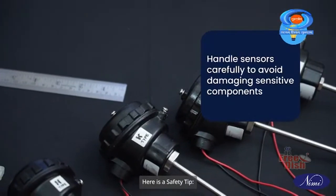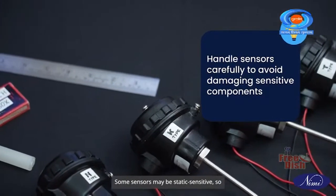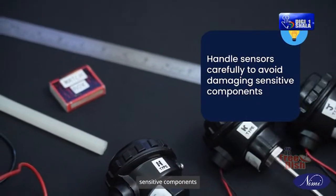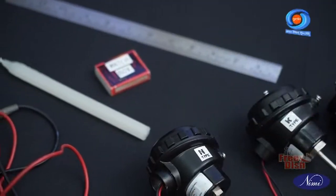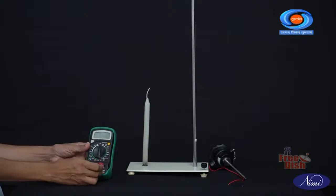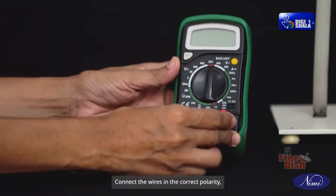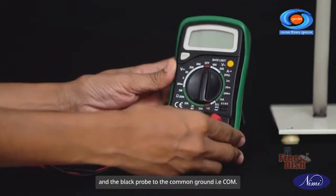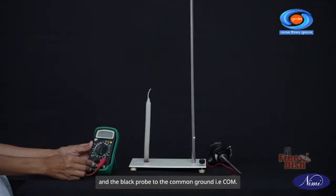Here is a safety tip. Some sensors may be static sensitive, so handle them carefully to avoid damaging sensitive components. The next step involves setting up the digital multimeter. Connect the wires in the correct polarity with the red probe to the V ohms milliampere port and the black probe to the common ground, that is COM.